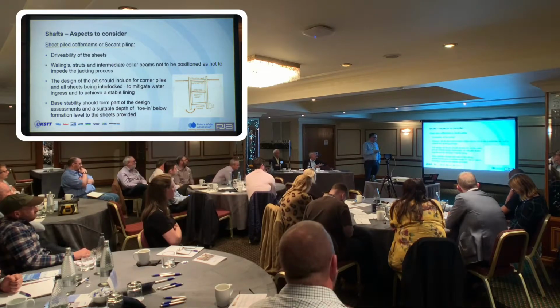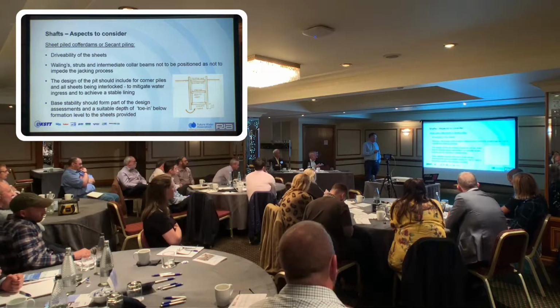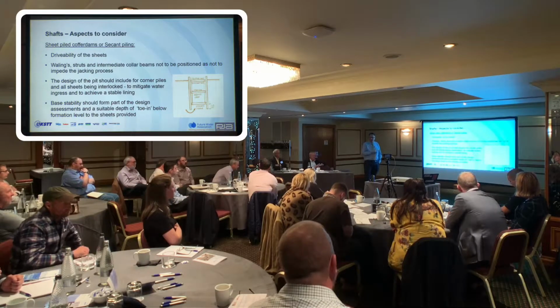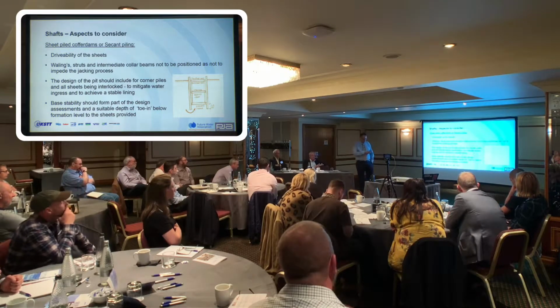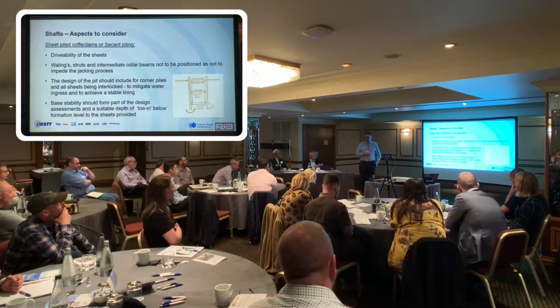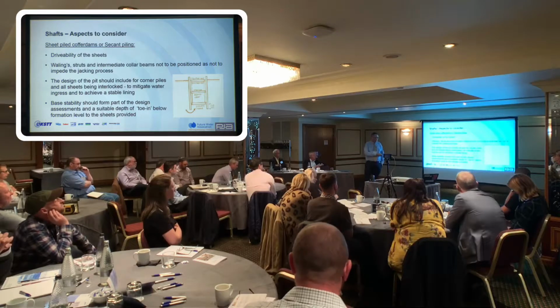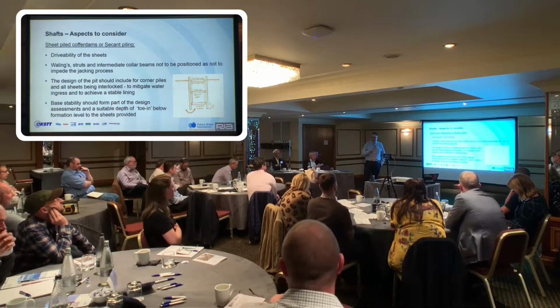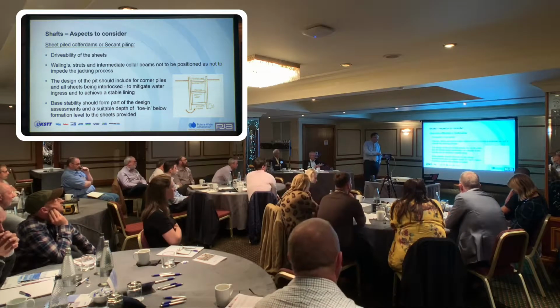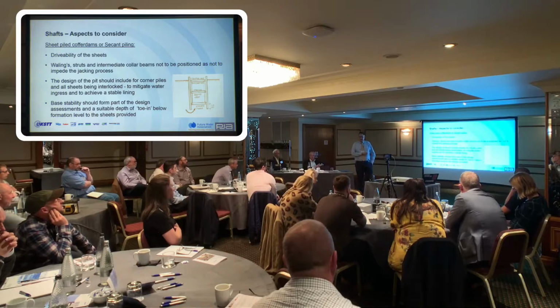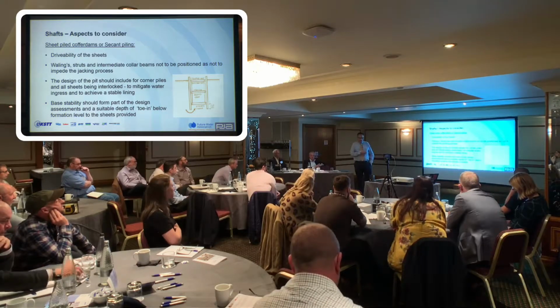And it's always important to think about base stability in the design. Again, I'm sure many of you have perhaps used the piling handbook. That gives indicative lengths. It actually gives a formula, I think, for working out the kind of toe-in depth that you need. It is a bit of a rule of thumb because you can do proper seepage analysis and things like that to advise on the water cut-off that you need.